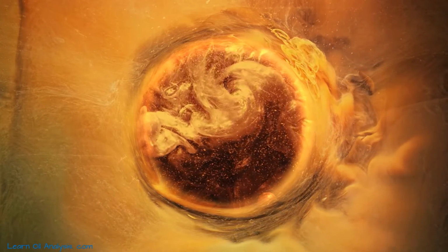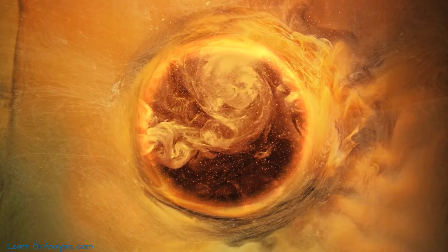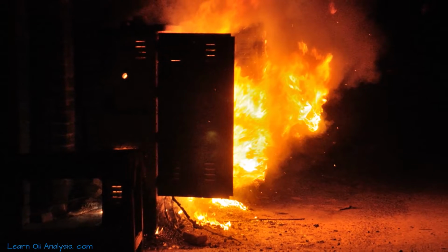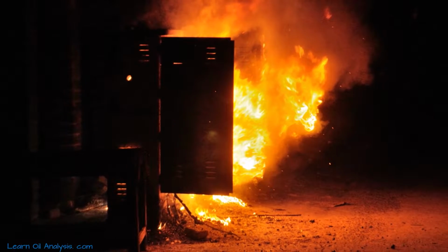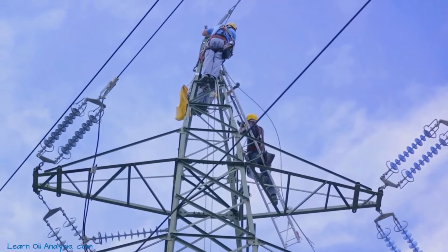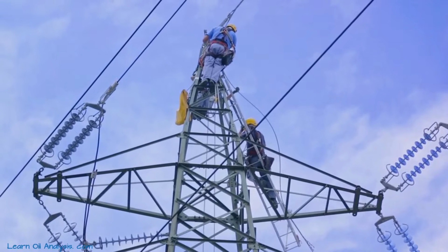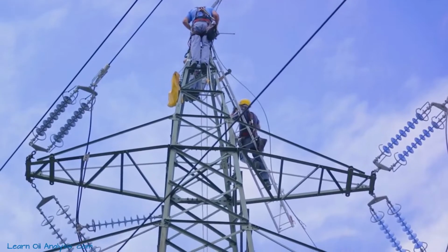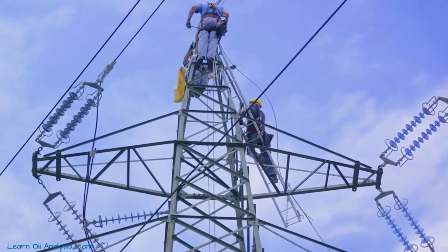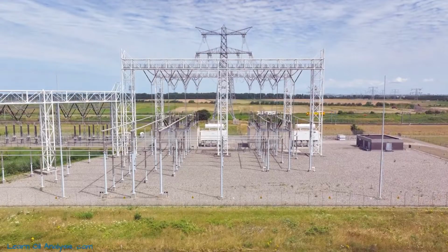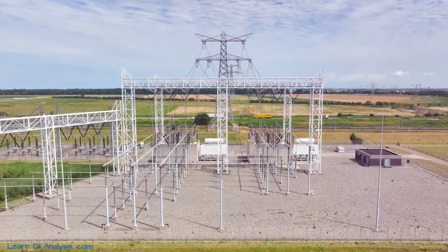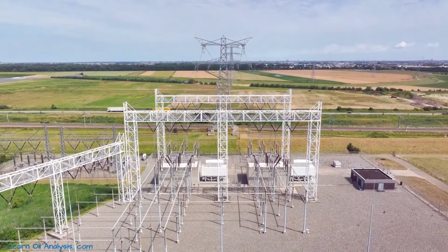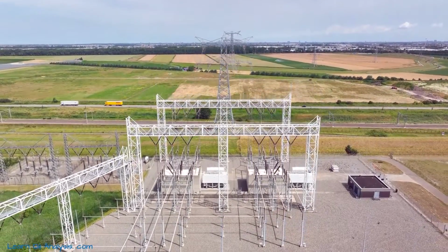Ignoring this could lead to catastrophic failure of the transformer, with potential safety risks and significant financial implications. So, in summary, high-energy discharges are severe electrical faults that cause extensive damage and carbonization within the transformer. They're characterized by high levels of hydrogen, acetylene, carbon monoxide, and carbon dioxide, and perhaps reduced oxygen, indicating the breakdown of both oil and paper insulation. Recognizing these signs early and responding quickly can save both the transformer and your pocket.